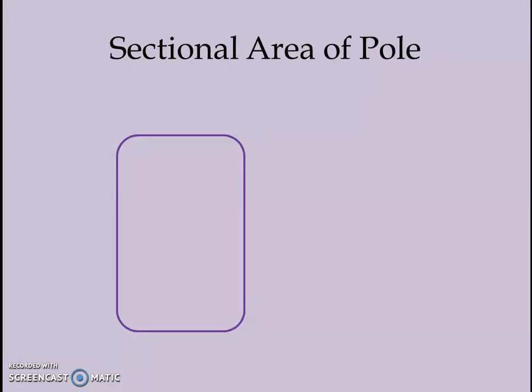We have two different types of rotor pole body. One is a rectangular shape. So this is the breadth of the pole, and this is the length of the pole. In case of axial length, it should be very clear to everybody that the axial length must be equal to the length of the stator core.